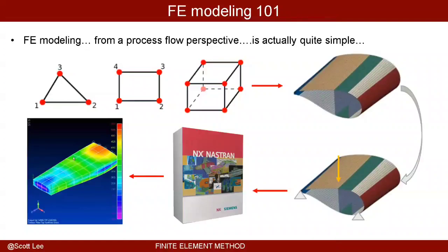And in this figure here, you see basically a trailing edge type of structure on an aircraft. And you just basically model that entire surface with shell elements, and it may be encompassing some triads as well. And you just stick them all together with nodes. And then what you essentially do is you apply your force, however your force is being applied to the structure, and you apply your boundary conditions.